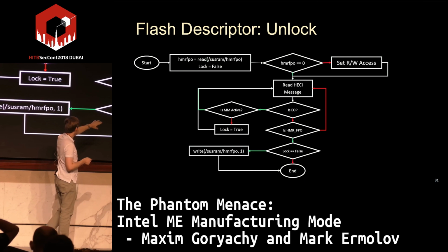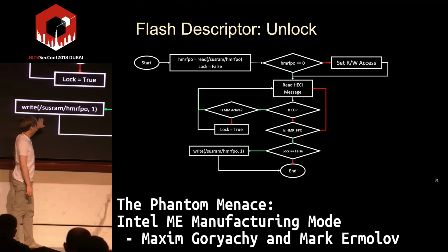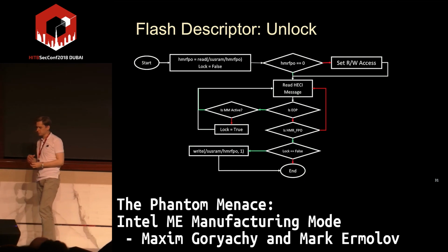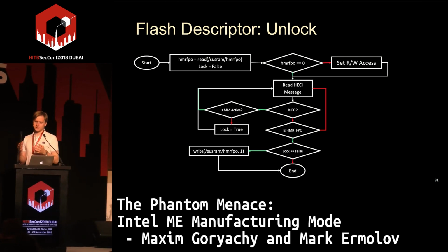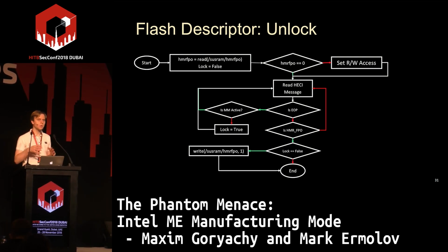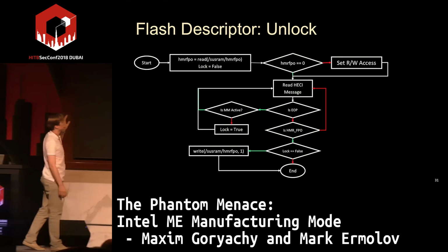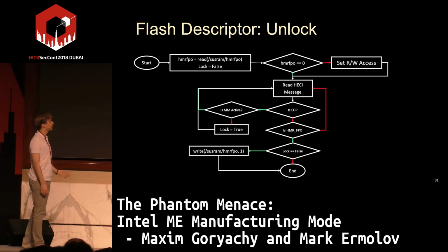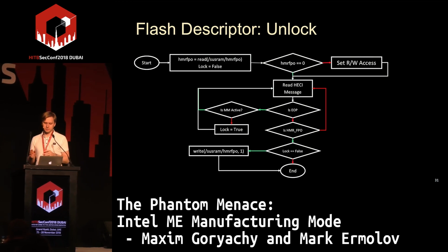If HMRFPO is received, ME sets a non-zero value in the file on the file system, and after that, on the next reset of the platform, ME gets access to the region because it sets read-write access in the SPI controller.